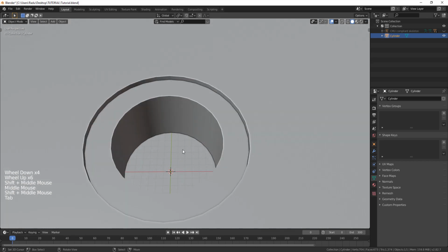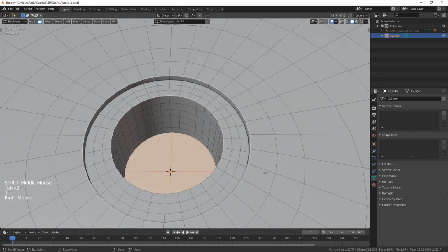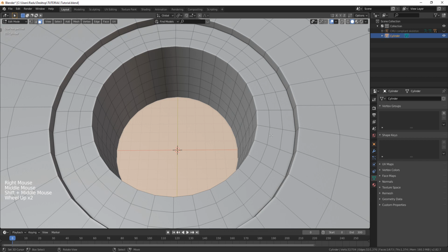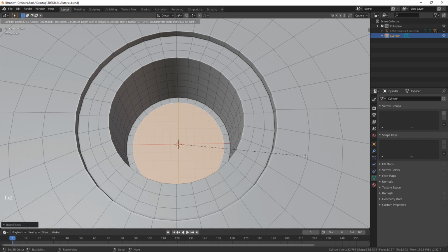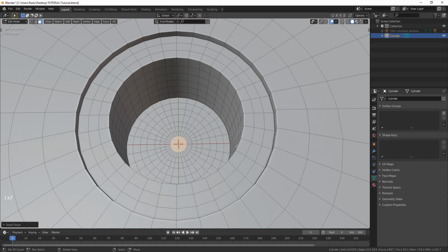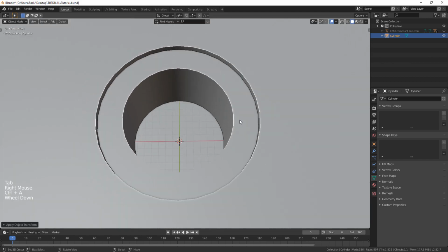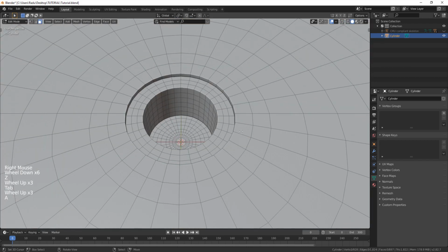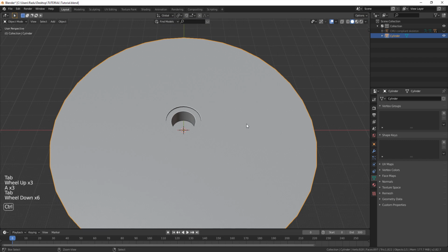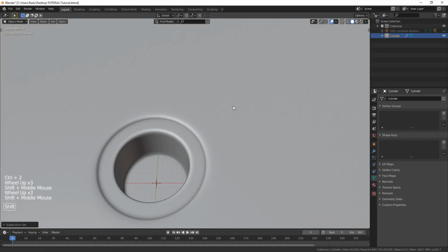And we are also going to do it like this, but instead of doing loop cuts, we are actually going to insert in this face. So press I, go a bit inwards, press I, go a bit inwards, press I, and so on. All right, now we have an evenly distributed mesh, and you can see we press Ctrl 2 to add subdivision,